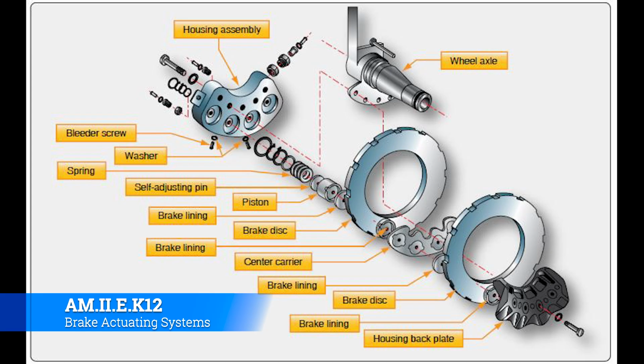Now, generally speaking, on like Piper Cherokees and Cessna 185s and things like that, you're not going to turn around and see multiple disc brakes. There's just not really any need for them. They already stop pretty well to begin with. You don't necessarily need to enhance that at all. Where you'll start to see these showing up is that the faster the airplane is, the heavier the airplane is, the more there's need for really substantive braking.